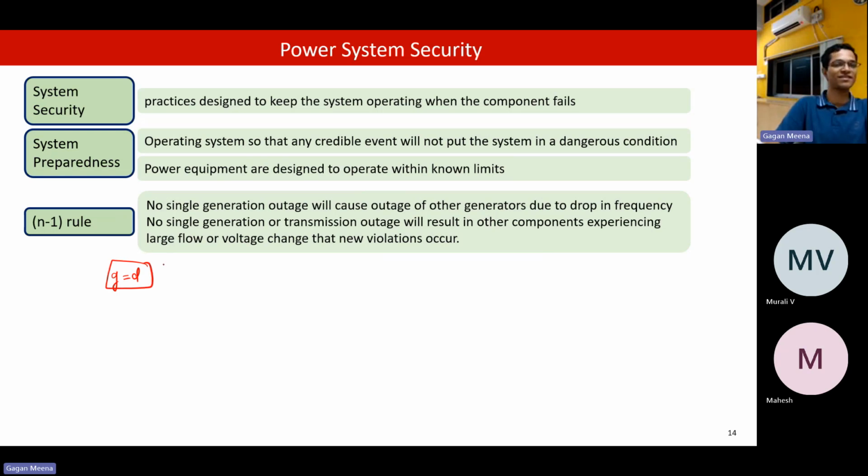The entire system is working very tightly to keep generation and demand in a very close, tight band. The frequency also has a very tight band, 49.95 to 50.05, a band of 0.1 hertz only. Ensuring that requires so much control.